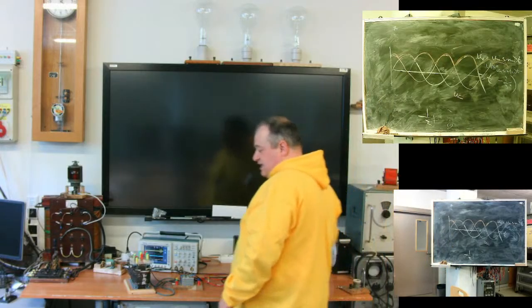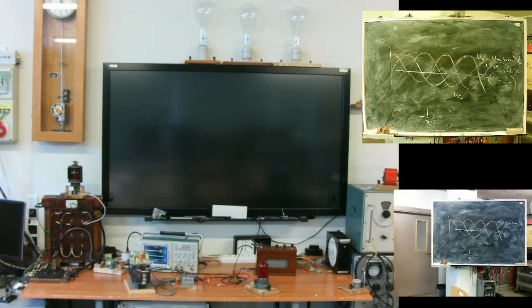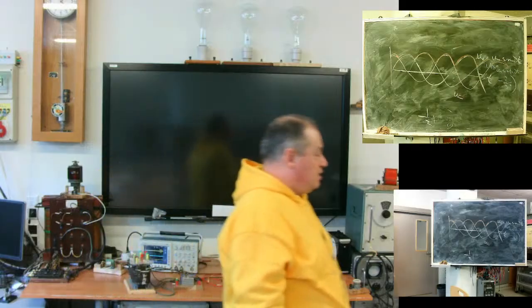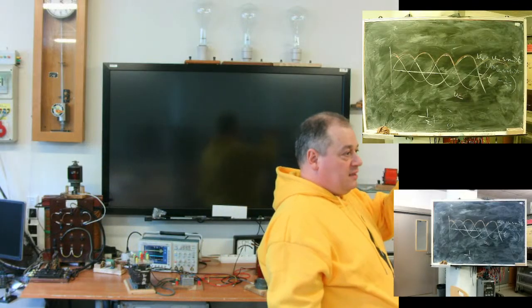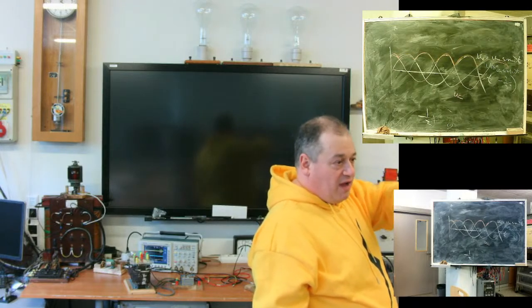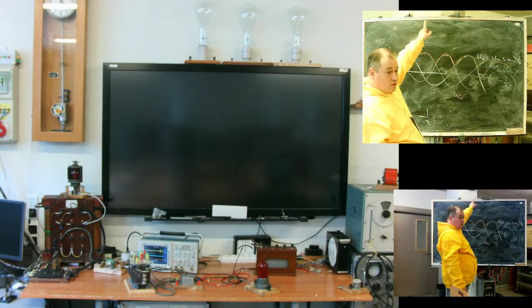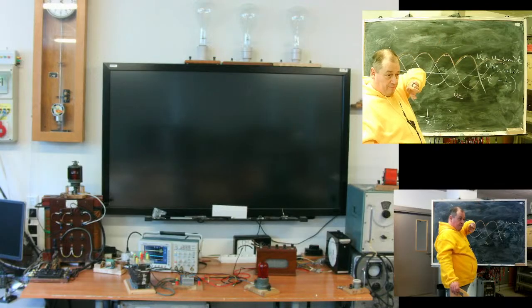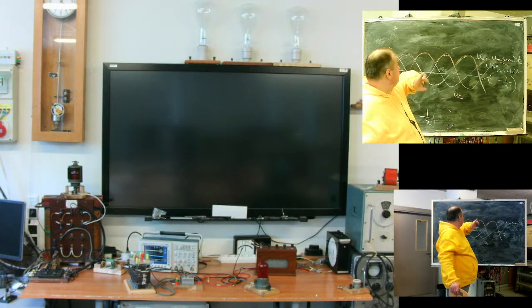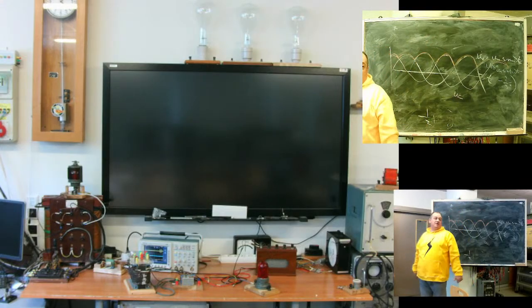Not everyone understands it, but in case of polyphase network, connection schematics of transformers are often called a group. Most popular are delta on 10 kilovolt or 11, star on 0.4, and group 11. What does 11 mean? If you put A phase voltage on 12 o'clock on 0.4, 10 kilovolt A-phase voltage will look at 11. It is a 30-degree shift between primary and secondary side.